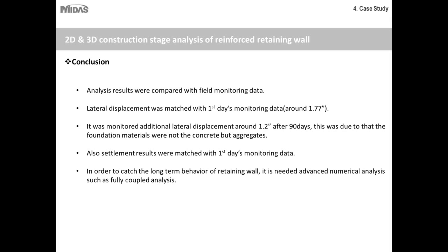So like I said, in order to catch the long-term effects of the retaining wall, it was needed to do advanced numerical analysis such as fully coupled analysis. So that led to an advanced set of analysis that needs to be performed, which is not commonly done when you are dealing with very conventional, simple, straightforward retaining walls.